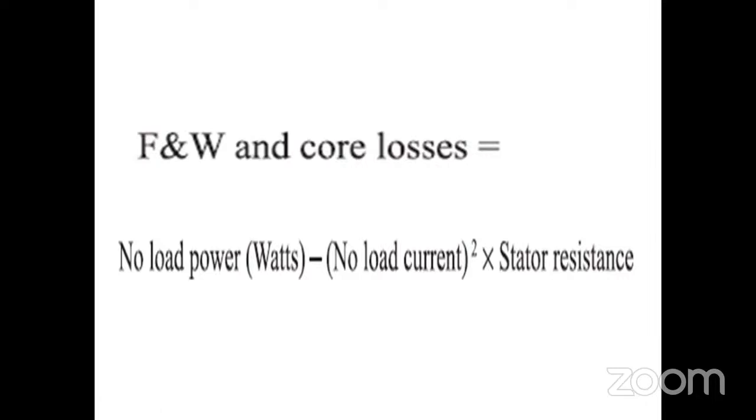So please pay attention to this formula. What is that friction and windage losses? No load power minus stator no load I square R loss. Okay, sir.